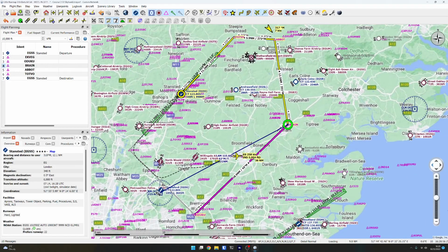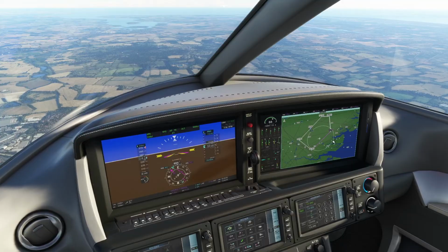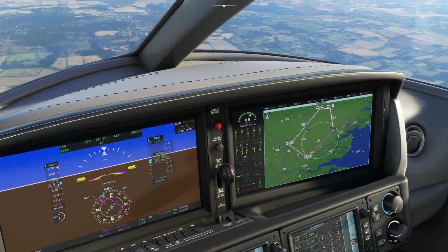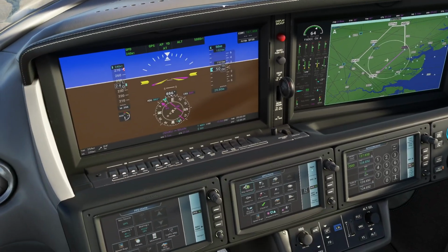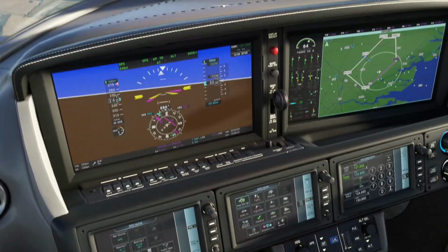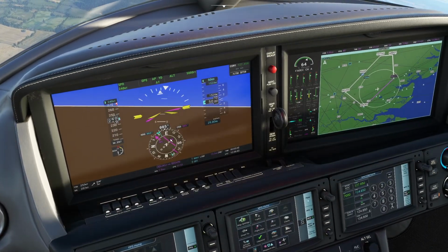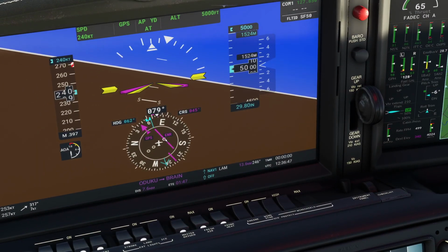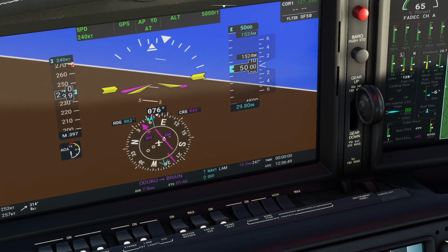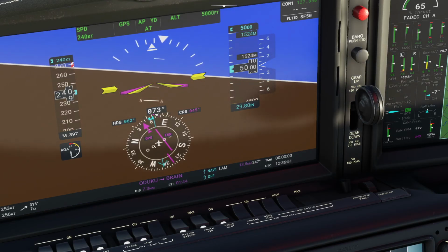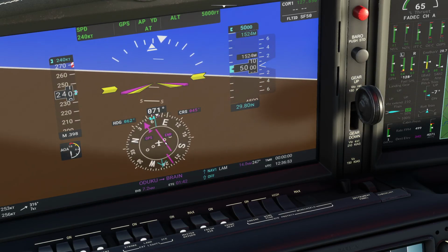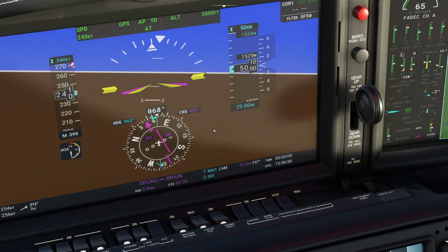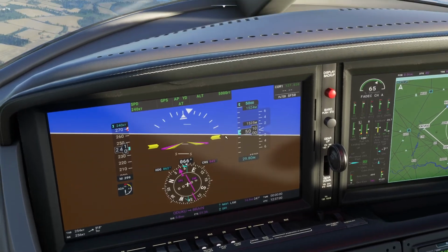So we're on this leg and we are doglegging across to get to the original flight plan line for Brain, but we're doing it under nav mode. So the airplane's doing it automatically, and here comes the course deviation indicator. So this line here that's sweeping in, that is the CDI, or the course deviation indicator. The entire gauge is the HSI, or horizontal situation indicator.